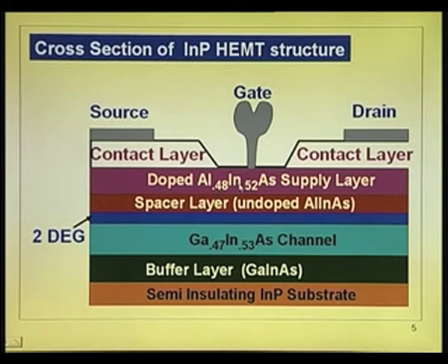Doped layer, how much doping you can put, of course, depends upon the Schottky barrier here. Okay, 1.46 electron volts band gap. Then on the top of that you see one more material layer is added, which you call the contact layer. The whole idea is to put a lower band gap material layer above the wide band gap material.